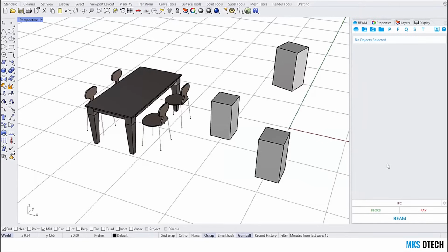It's very fast if you're sending curves and points to someone else to pick up in Dynamo. For example, if someone is doing fabrication, you can send the curves so they can use them. Instead of sending the file, you can send a BIM file, and they can access it in Dynamo and do whatever they need to do in their file, sync into BIM 360, and you get your content. That's also possible, and we've seen that done in a few projects.